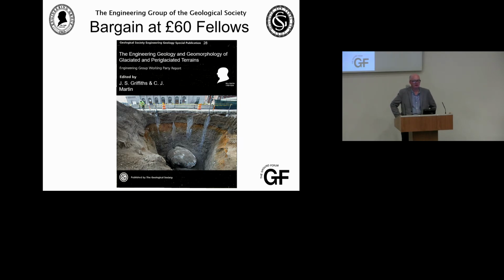It is a very large drop stone in some glacial lacustrine deposits, surrounded by some tills. Everything in that hole varies on the half a metre scale. And they were about to put down a piled construction there, and there was this great massive lump of rock. So it really exemplified what we were trying to achieve by demonstrating lateral and vertical variability.